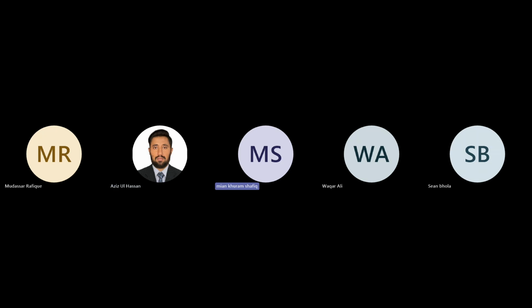If I see your formula, VOC cold is equal to KU multiplied by VOC, with KU equal to 1.0634. KU basically is a constant, the multiplying factor we get for the voltage increase.